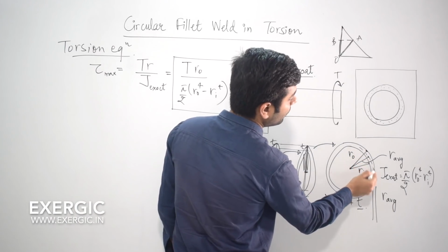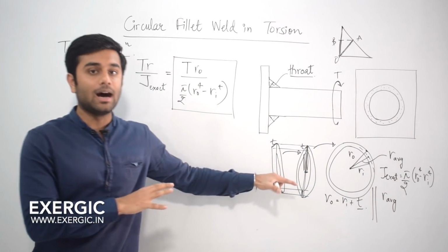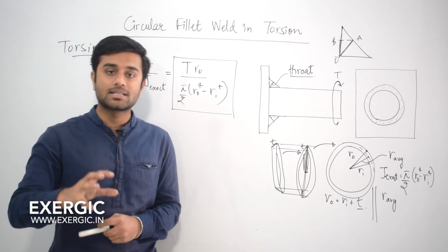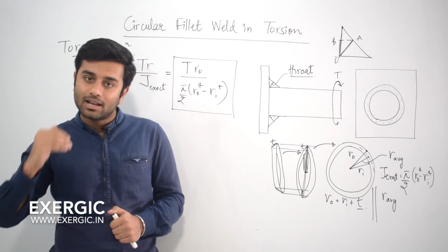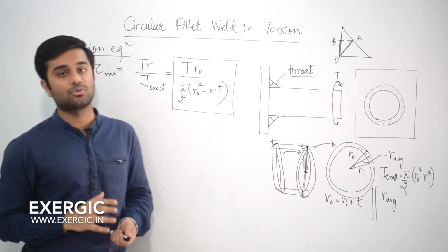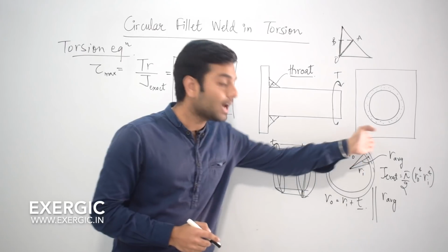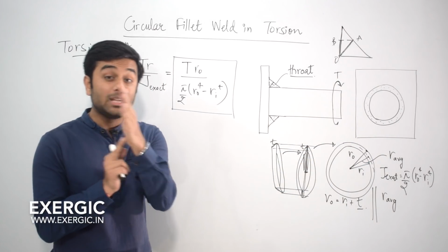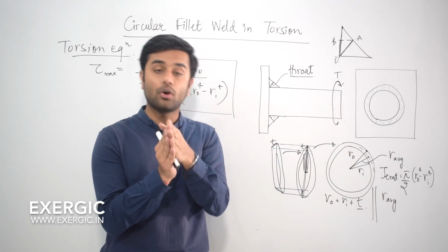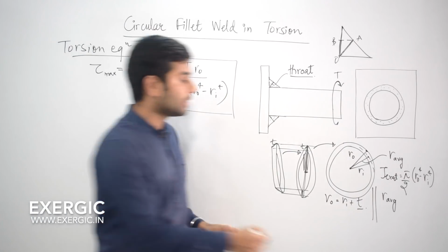and it's important for you to clear the concept of average R here, because this is something which confuses many aspirants, and there has been a question in other parts of the syllabus where inner radius, outer radius and average radius has created confusion among aspirants. So it is important for you to listen to this carefully, that the average value of R here is lying between RI and RO. So it is at a distance of T by 2. You add T by 2 to RI and you will reach R average, or you decrease T by 2 from RO and you will reach R average. So this is how you can define R average.